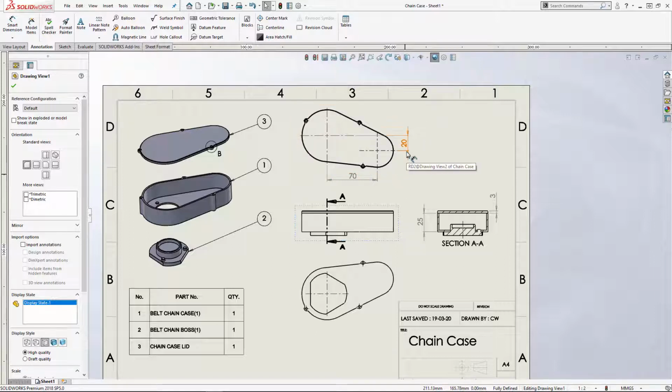So the thing that we get into is, how do you change the colouring of any given drawing element? So how do you change all these dimensions that we want in black to black without manually doing each one separately? So one easy way of doing that is you place all these dimensions on a separate layer of the drawing, and then you assign that layer of the drawing a specific colour, and then anything that's on that layer will follow that colour. So we're going to edit the layers now.